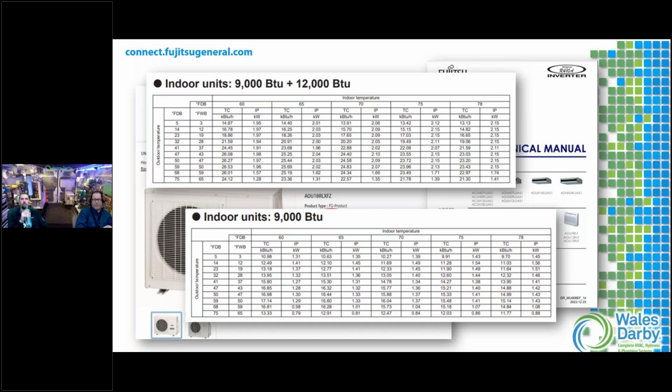The outdoor heat exchanger is. So now you're limited to that outdoor unit. Correct, the sizing and selection. If it's 24,000 BTUs, that's what you get. We're allowing you larger connectable capacity. Exactly. But then you're limited by your installed lengths, distance, and insulation, all the things Rick was just stating.